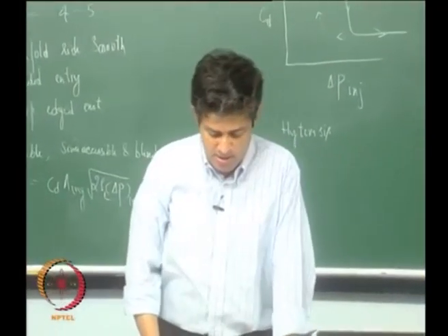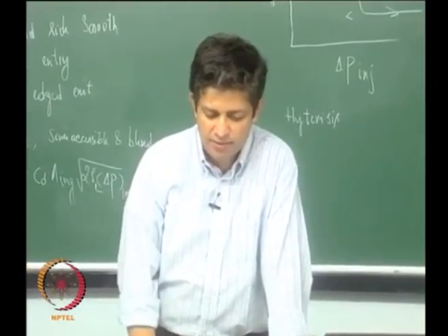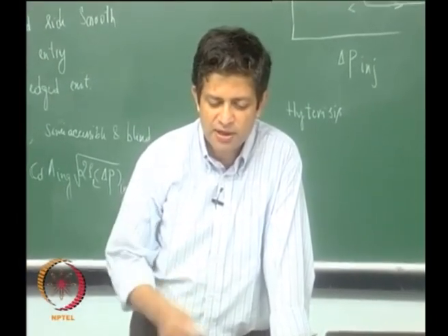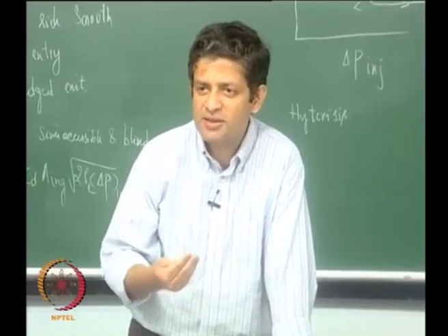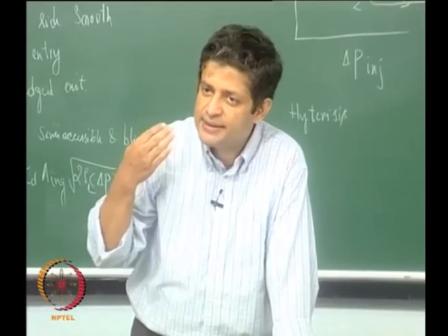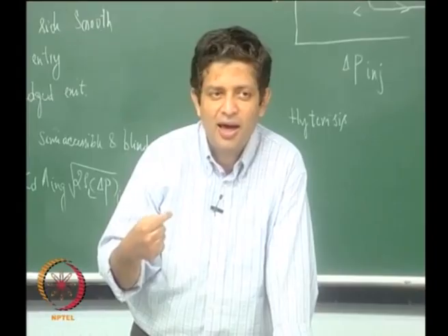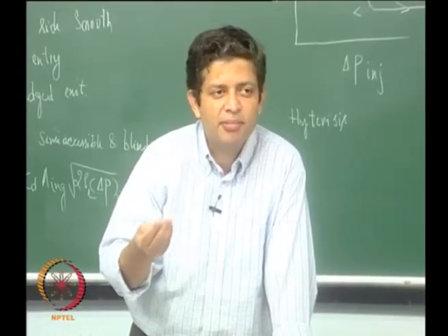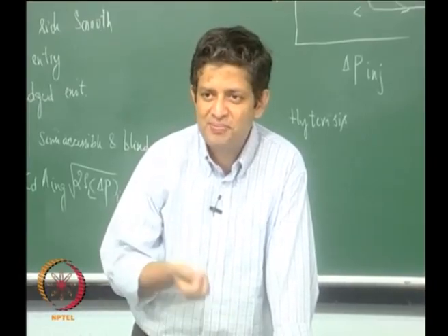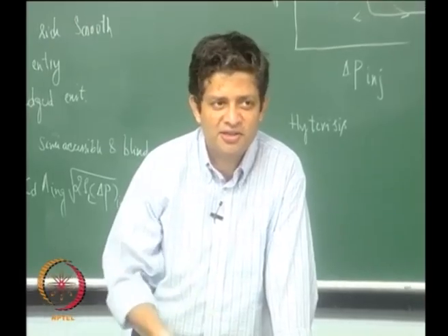Now as I said earlier, the things that control the droplet size are the injector diameter and the interplay between inertia forces, viscous forces and surface tension.